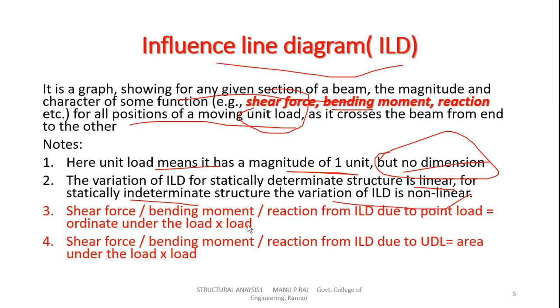Also, shear force or bending moment or reaction from the ILD due to a point load is equal to the ordinate under the load into the load. I will explain this with an example. And also shear force or bending moment or reaction from the influence line diagram due to a UDL is equal to the area under the load into the load.